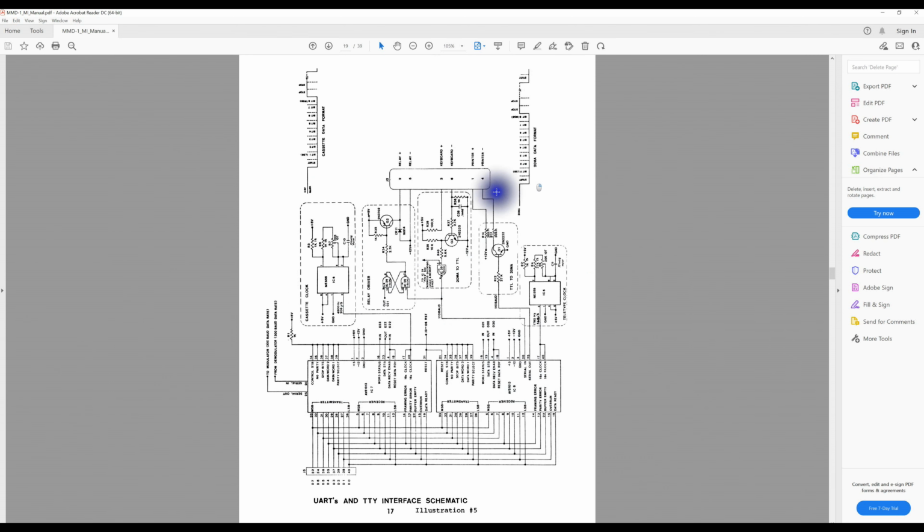serial drivers. So here is the relay plus and minus, keyboard plus and minus, and printer plus and minus apparently in their paradigm. So interesting that you could drive the relay. This has got to be 20 milliamp. Looking at it, yeah, 20 milliamp data, cassette data format. I guess it's really both.